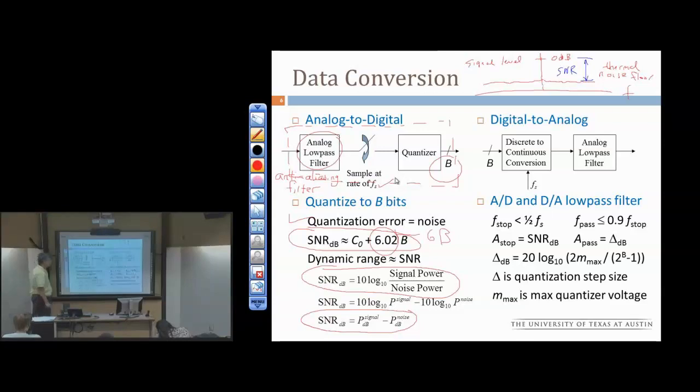So again, if my SNR here, with respect to signal level versus thermal noise, matches the SNR of signal level versus quantization noise, then all my bits are good. Another way of saying it is, if I tell you that the SNR of signal level versus thermal noise floor is, say, 60 dB, then I know I got how many good bits if I quantize? 9 or 10, depends on C naught. Right? So if C naught were 0, I'd have 10 bits.